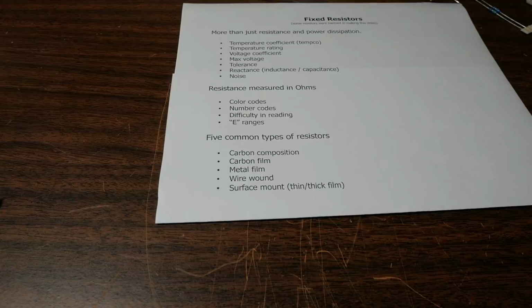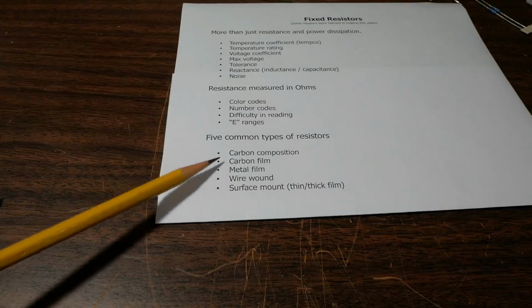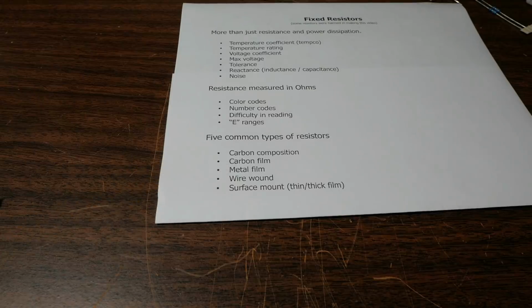So now let's take a look at the 5 common types of resistors. Like I said, there's other types, but these 5 are probably the ones you run into 99% of the time. First up is carbon composition. These, although they're still available, have fallen out of favor. Not as common as they used to be. They were very common. If you repair old radios and TVs and things, you see these used quite a bit